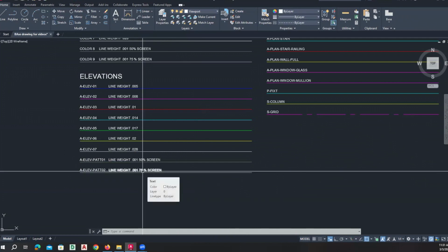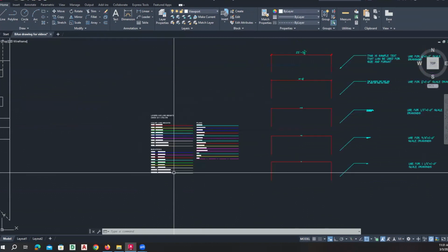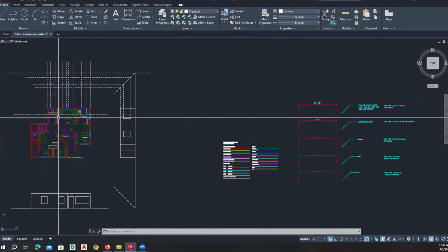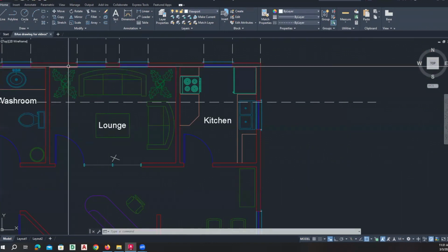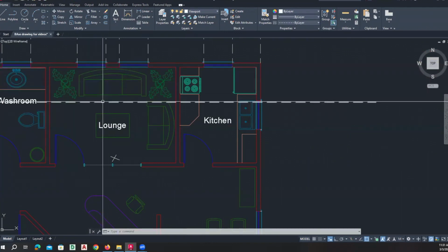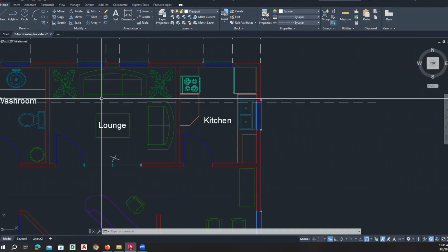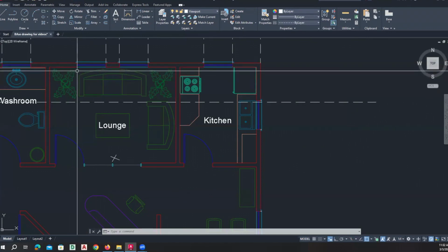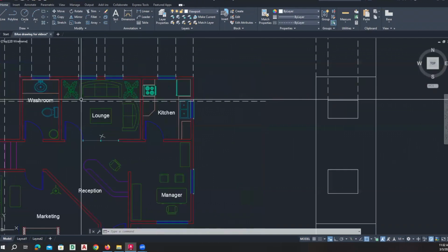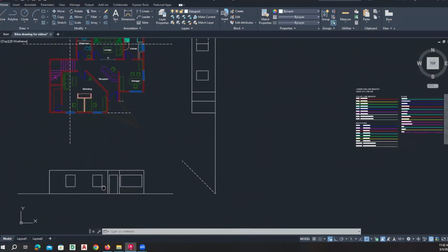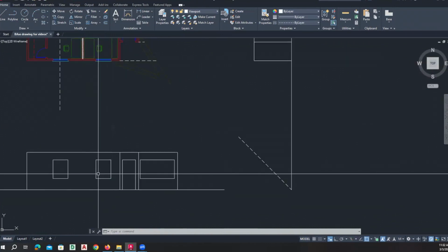Things that are in detail, for instance, if I'm drawing a trim, there's no trim in this drawing, but sometimes around the windows there is trim, right? I might draw some of the details of the trim on one of those layers. The outline of the trim may be on a light layer, like 01, but the trim details, like the little fluting, maybe I might put on a screen layer, right?